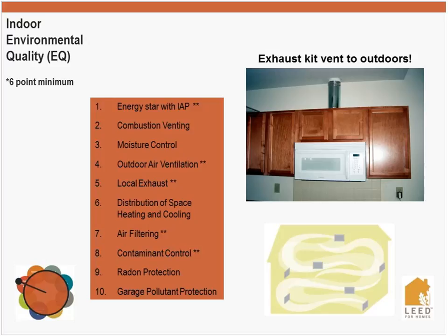We're looking at bringing in makeup air. We're really looking at local exhaust, so having the kitchen range hood and the bath fan both venting not into the attic, but actually outside of the house. Venting into the attic causes a lot of issues, so we're going to be looking to see all of the bathrooms have proper ventilation, get some extra credit if you add on motion sensors or humidistats. This is another place where you could do balancing to ensure rooms are receiving proper airflow for comfort, duct sealing. We're going to be looking at MERV filtration, MERV-rated filters.